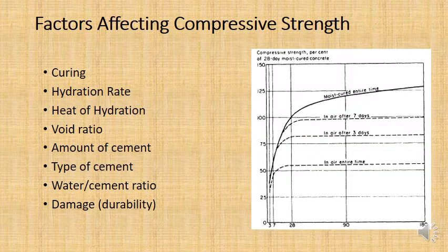So there are a lot of different things that can affect the compressive strength. Now, one of the ones which we already talked about was curing. Basically, the longer you cure your concrete, the longer the cement molecules will have access to water to react with and form those strong hydraulic bonds in your hydraulic cement. Now, that's very important.